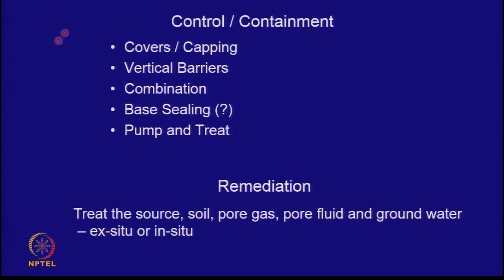This is where geotech engineers have a lot of role to play. If one goes for remediation, it's a different problem altogether. You have to treat the source, you have to treat the soil, you have to treat the pore gas, the gas in the pore space, you have to treat the pore fluid, and you have to treat the groundwater. Pore fluid may not be groundwater, it can be some other fluid. And this treatment can be done after excavation or extraction, that is called ex situ, or you might want to do the treatment in situ. So we'll look at these two separately.